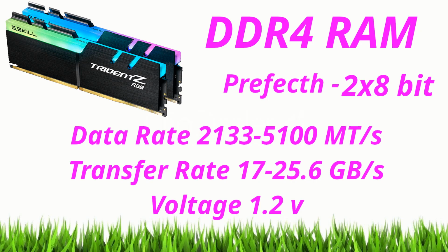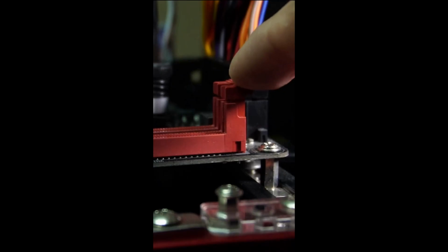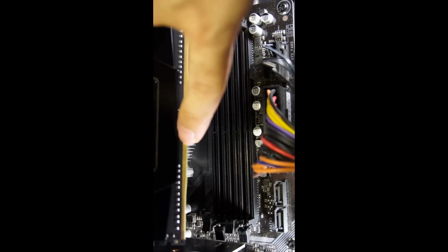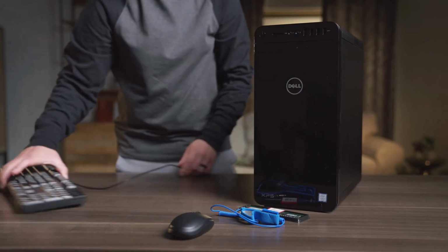This newer generation also introduced bank groups to avoid having a prefetch of 16, which isn't desirable. With bank groups, each group can execute 8 bits of data independently from the other, so DDR4 can process multiple data requests within a clock cycle.